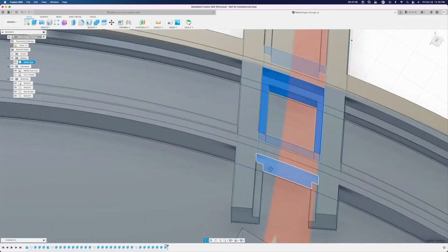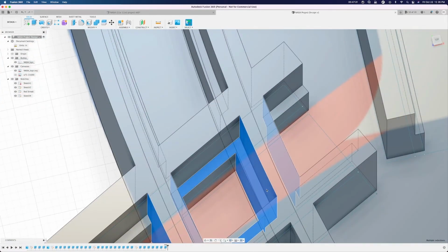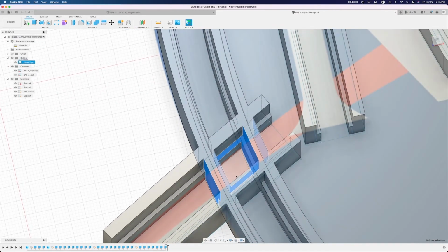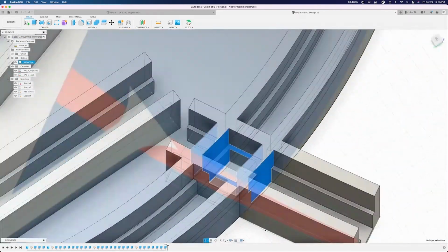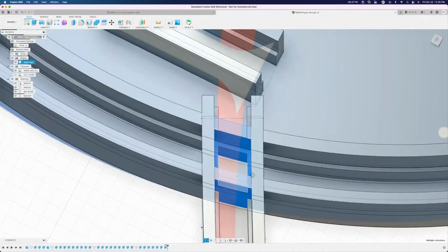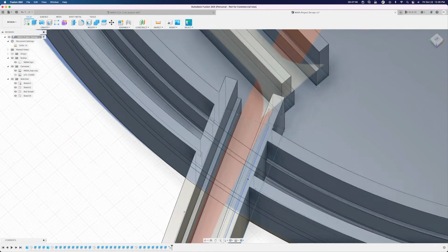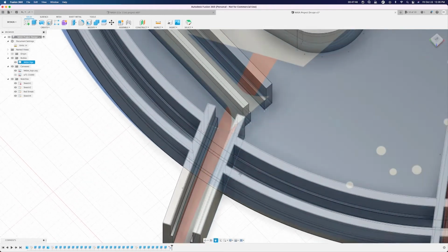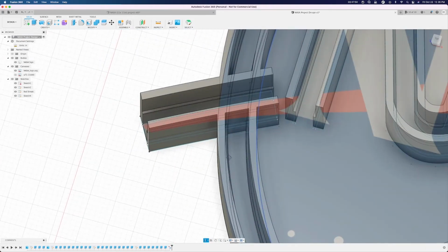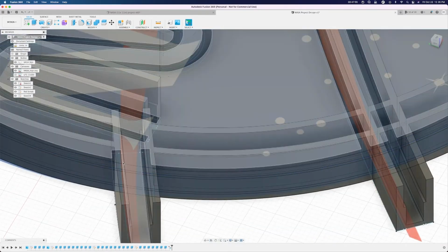This side. And by the end of it, you should have something that looks like this. Now I'm holding shift on my keyboard to select all of these options here, and I'm just scrolling around so you can see exactly what this looks like. Okay, on your screen you should have something like this selected. From here, I'm gonna press delete on my keyboard, and Fusion 360 will know that I want to delete those faces. And you can see this does not affect my existing design, other than just actually deleting those faces that were right here.